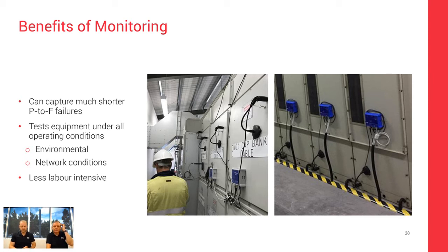At times we're going into particular substations every month or every 3 months. If you're going into the same substation month after month, potentially detecting nothing, the veracity of the survey has a tendency to slip. You start becoming blasé and stop paying quite so much attention, whereas a permanent monitor is sitting there doing its job.